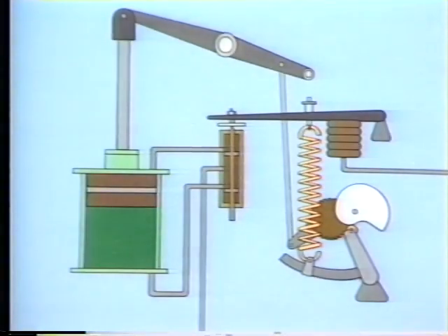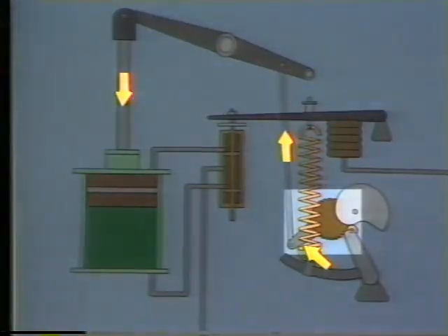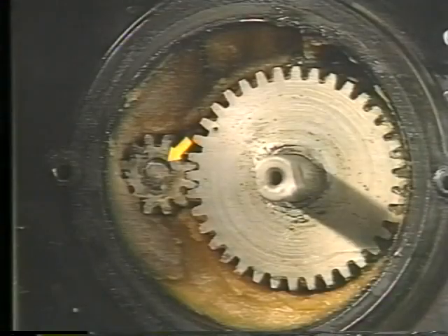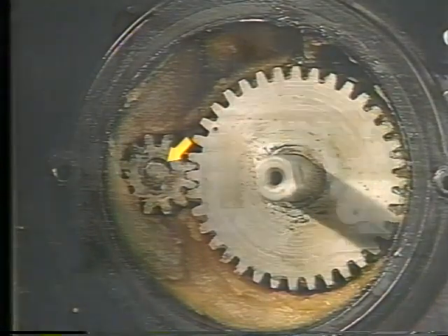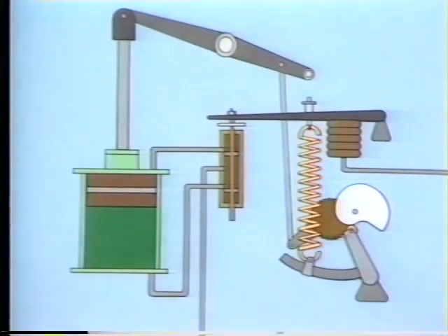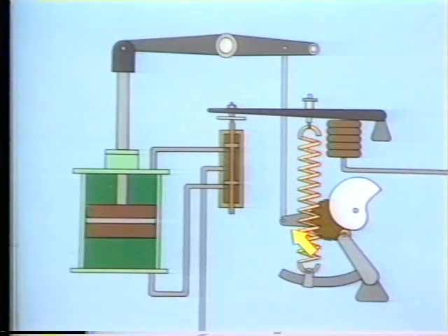As the piston rod and its connecting linkage moves, it rotates this drive arm and these gears. The smaller gear is mounted to a shaft that extends through the positioner case and is connected to a cam. When the piston rod and its connecting linkage rotate the drive arm, it causes the cam to rotate. So this gets us back inside the positioner, where we can describe the rest of the balancing mechanism.